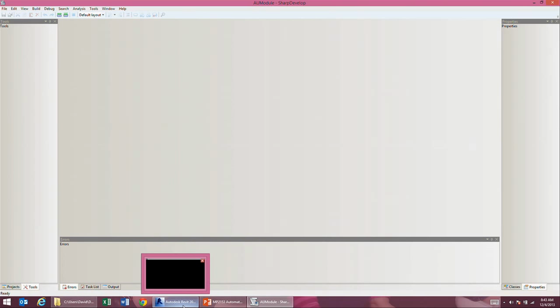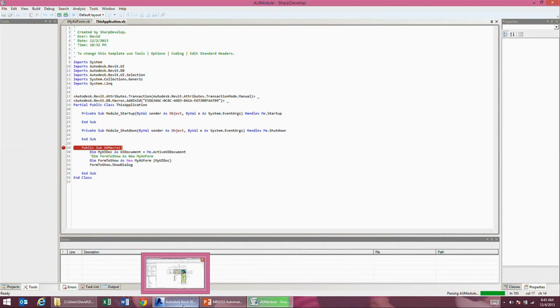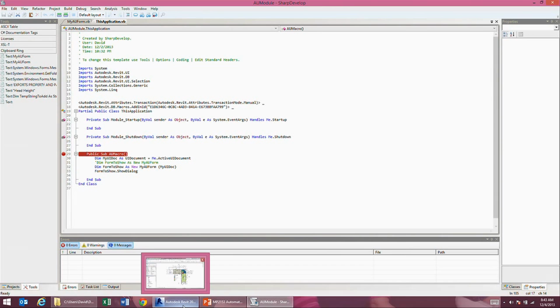Is the API different for the different versions of Revit? Yes and no. Basically, if you're going to run a program on Revit 2014, you have to reference the Revit 2014 API. Now, if you've compiled something in the Revit 2013 API and it doesn't use any new functions, there is a possibility that it will continue to run with the same compilation in 2014, but I wouldn't recommend it. Essentially, you need to reference the latest API DLLs, make sure that you've got the latest revision of the functions and classes, because whenever it's calling an API function, it's going to be calling it from that version's DLL. So if you call something incorrectly, you're going to crash your program.